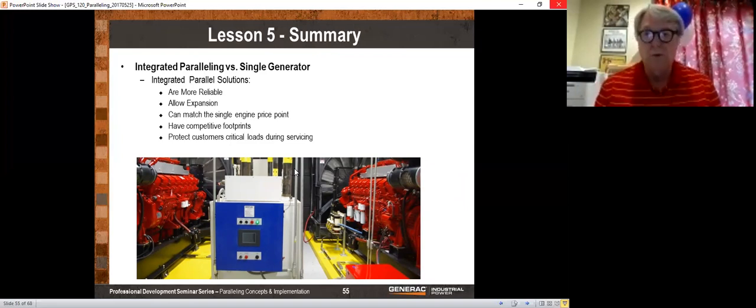And we basically go out, hook our laptop into the unit, and take a look to see if we've had any faults from the past. We again check things like batteries, battery chargers and block heaters, and, like in your car, we do a number of checks there, but we don't actually change the oil or anything like that. Then 6 months later in the year, we would change the air filter and the oil filter. If there's any water in any of the fuel filters, we would drain those, and we would do what you do on your car when you take it in for an oil change.